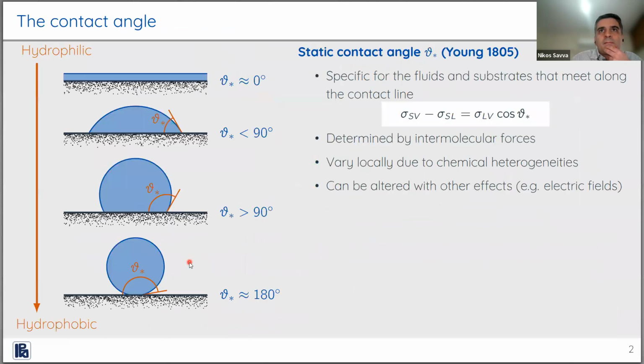So basically, let's look at this configuration. Typically you coat the surface with a dielectric. The droplet is usually conducting, okay, and then you apply electric fields, and due to the attraction of the charge, Maxwell stresses are generated on the free surfaces that attract the liquid toward the electrode.